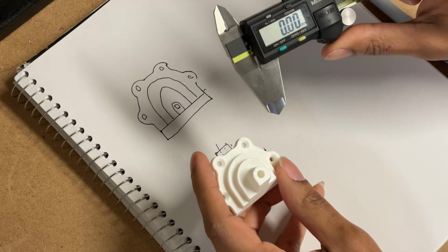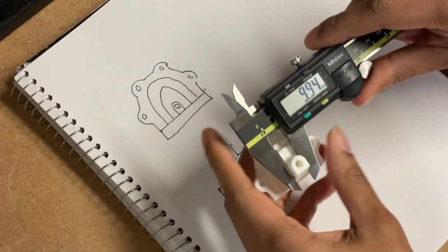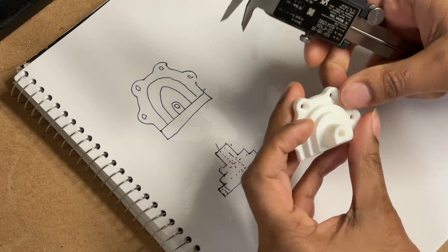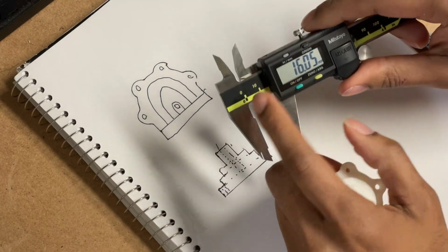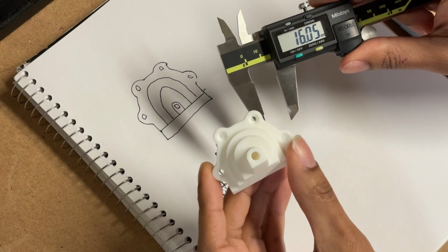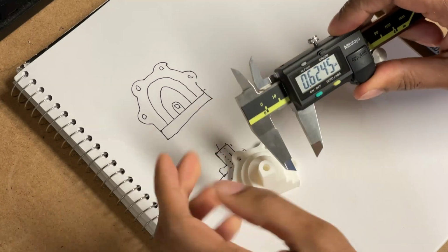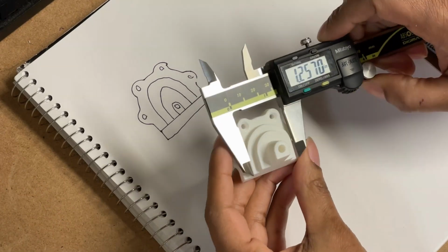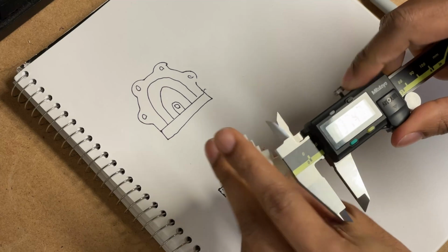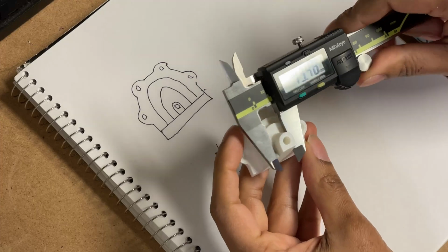The caliper can measure in a few different ways. The most typical one is the outside measure, right? Okay, so there we got 9.94 millimeters. Before you start reverse engineering, or somewhere in the process, it might be a good idea to figure out, did the previous designer design this part in imperial units or metric units? Maybe take a quick couple measurements and see what makes sense. 1.2. Just given that first reading, I'm gonna assume that this was made in metric units.